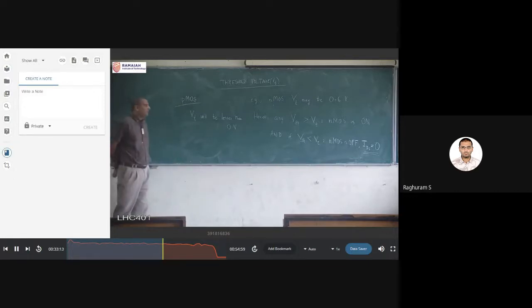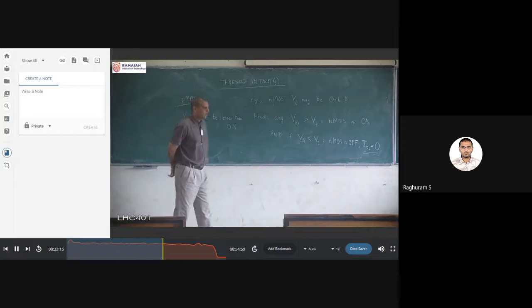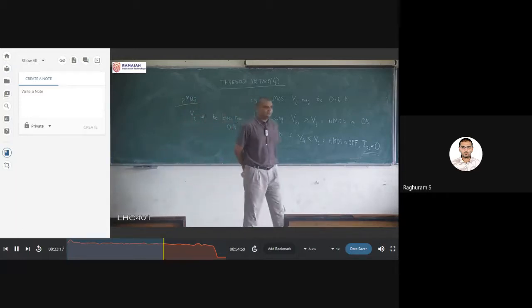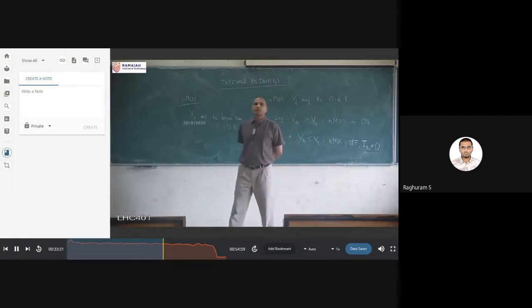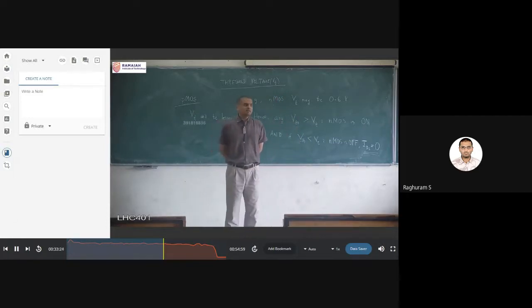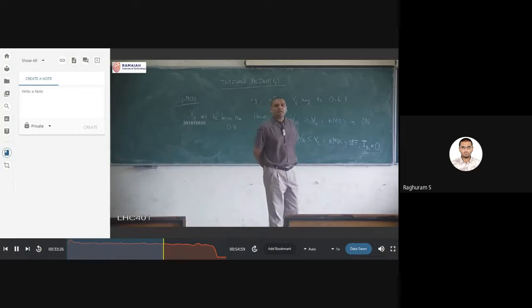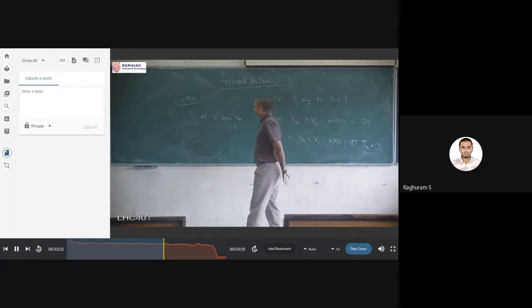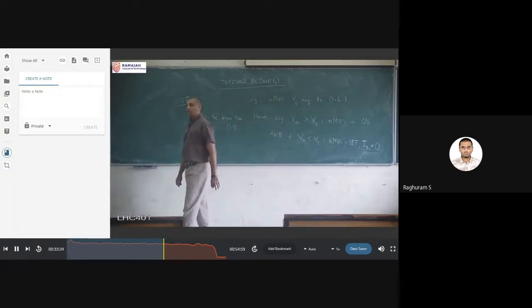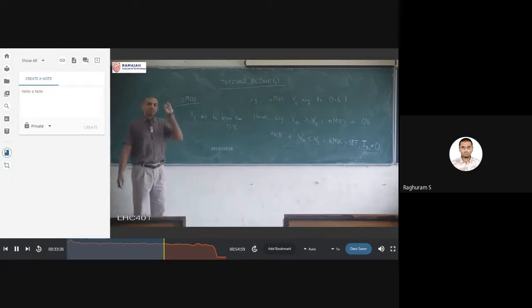Now, you can definitely ask me: since the beginning of this class you have been saying only two voltages, 0 and VDD. Suddenly, if I want a negative voltage for a PMOS transistor, where will it come from? Good question. We will answer that shortly, but just remember for now that the threshold voltage of a PMOS transistor will be a negative number.